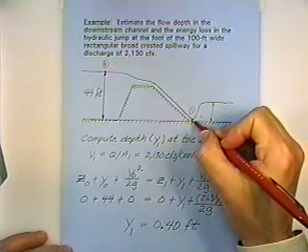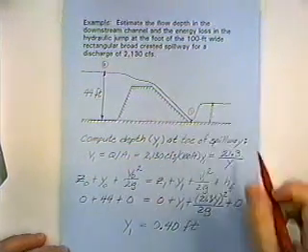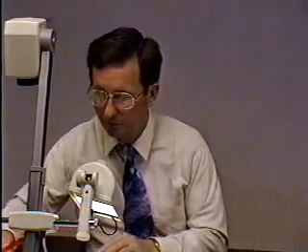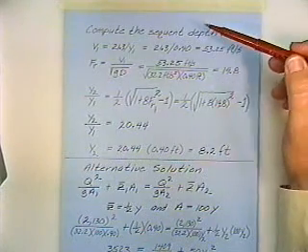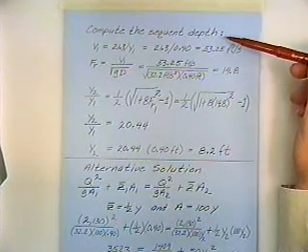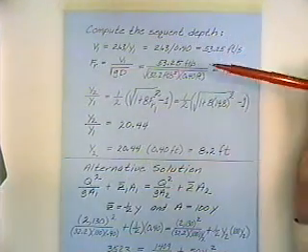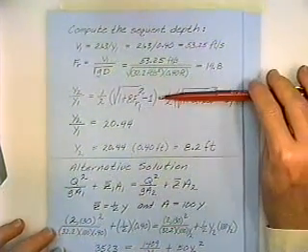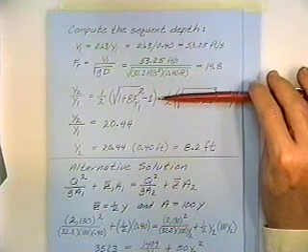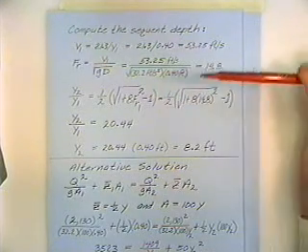Knowing the depth here is 0.4 feet, we want to get the depth here using conservation of momentum. In other words, we want to compute the sequent depth. And so I'll use this basic equation. And so we want to compute the sequent depth, and here's the basic equation reproduced from the previous page of the notes. That's for a rectangular channel.